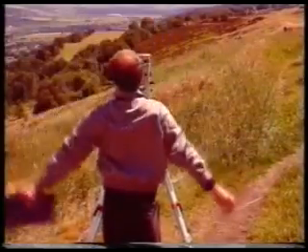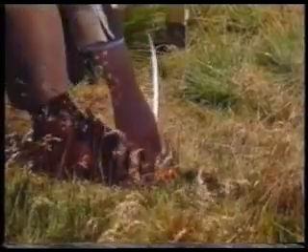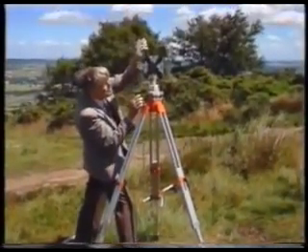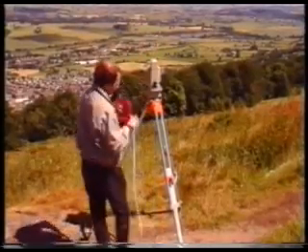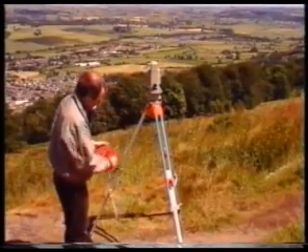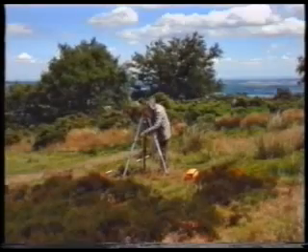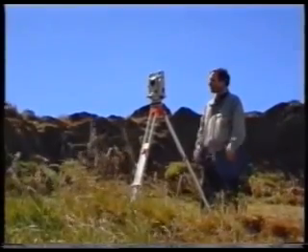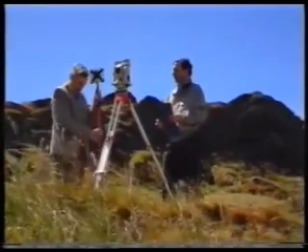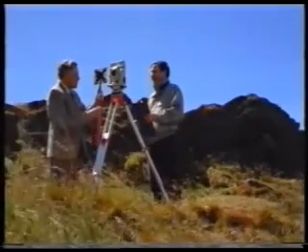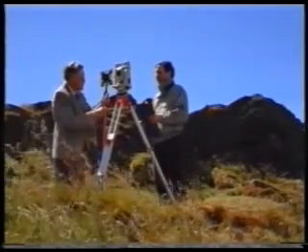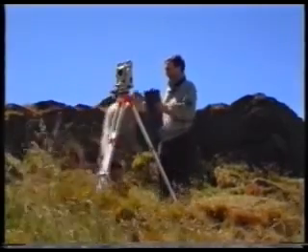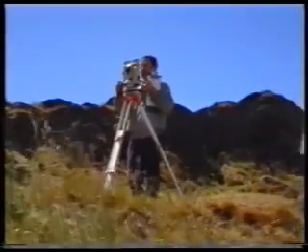Finally, before moving on, the height of the reflector above point B and the height of the EDM unit above point A are measured with tapes. These enable height differences and reduced levels to be calculated. An alternative method of mounting the reflector is to fit it to a detail pole. This is ideal for use either in detail surveying to establish the positions and reduced levels of features, or when setting out design points on site.